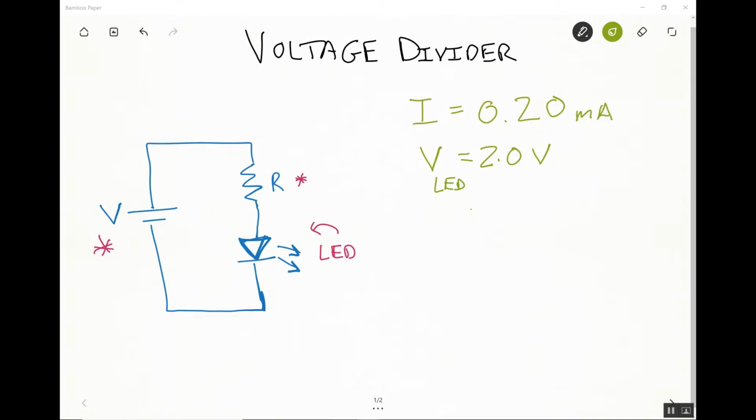All right. Okay, so here is a green LED, a basic green LED. And if I click on documents, there's a data sheet here. Let me bring it up. And the data sheet has a bunch of parameters for this LED. One of the things you need to be able to do is to look at an LED data sheet and pull out the information that's essential for designing a circuit with a current limiting resistor that'll make this LED work. All right, so the things that are important here are the stuff that's contained in this table, absolute maximum ratings.